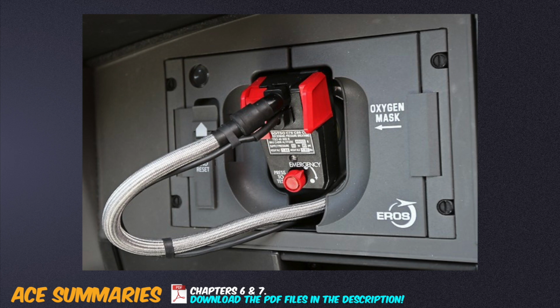In the worst possible scenario, for example, depressurization above high terrain. In the normal setting, the oxygen masks deliver sea level pressure oxygen mixed with cabin air. Since oxygen is 21% of the atmosphere and the sea level pressure is 14.7 psi, sea level oxygen is at around 3 psi.